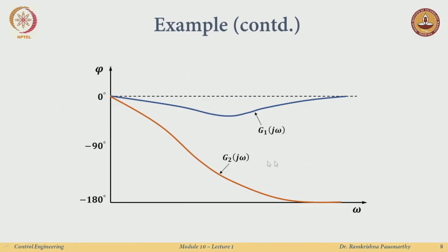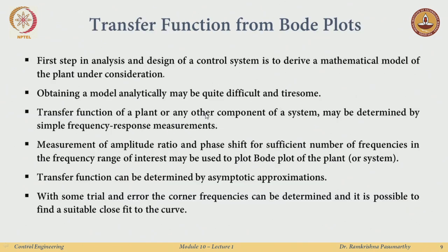Okay, so the range in the phase angles, here it goes 0, say minus 45, and here it keeps on going down. So, this is the minimum phase system, and this is the non-minimum phase system because of the range also of the phase angles. So, if I do not know the number of q's and p's, I need not always uniquely determine it; I can make use of the other definition.